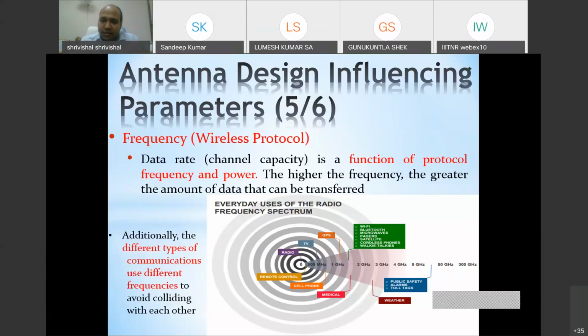So once you go to the design, you have to face these kinds of challenges. So it will always be a trade-off. That's why, if you see, a lot of local applications or wireless personal area network applications have been placed in the 2.4 gigahertz ISM band, even though we already have some additional ISM bands available in the lower frequency bands. At 2.4 gigahertz, we get an optimized antenna dimension, which could be placed with this kind of system, and with those antennas we can move on. Also, the flexibility of moving those antennas is a little bit easier.